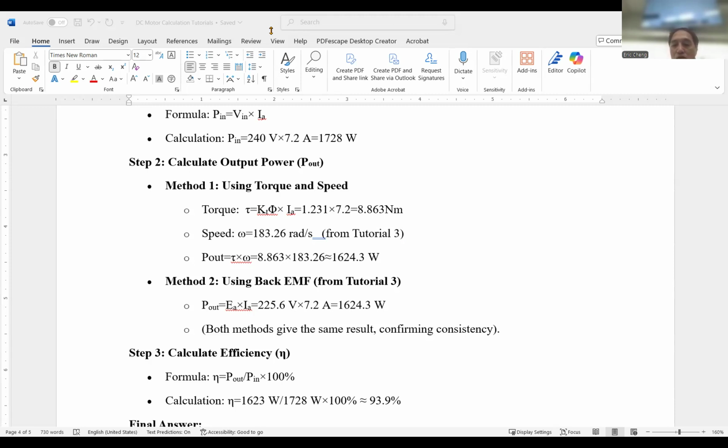So the torque we are having: then we take the armature torque constant, 2 multiplied by 100 amp, which gives you 200 Newton meter. So that basically is how we calculate the torque, using the back EMF equation and the torque equation.